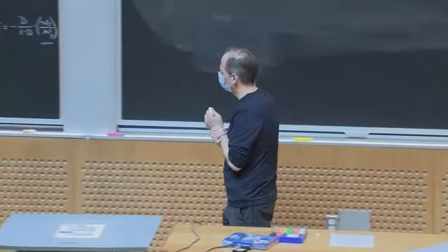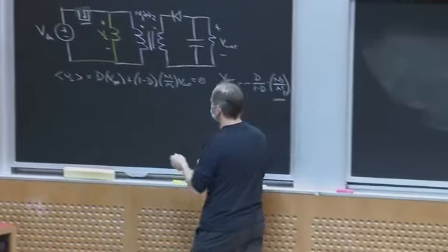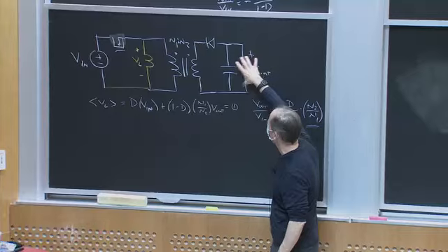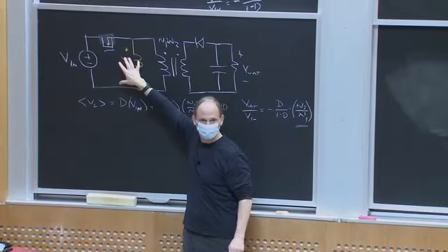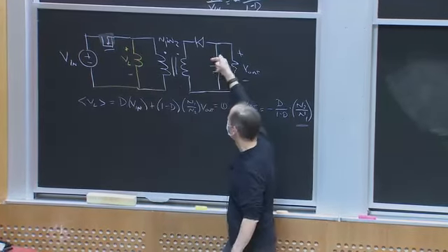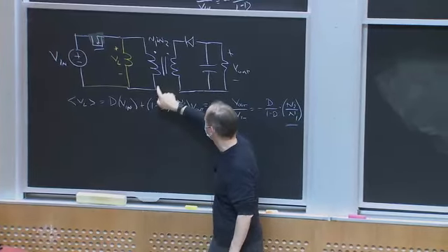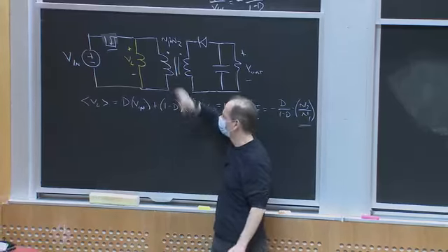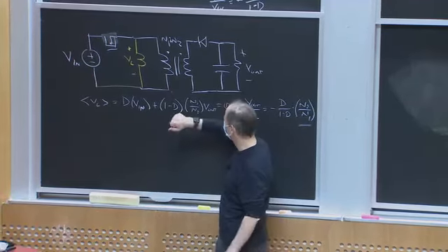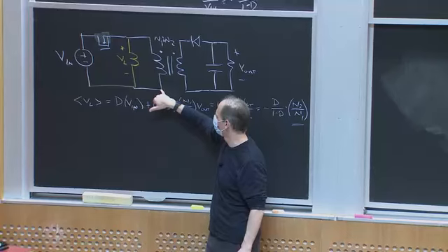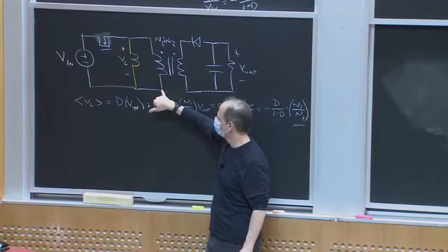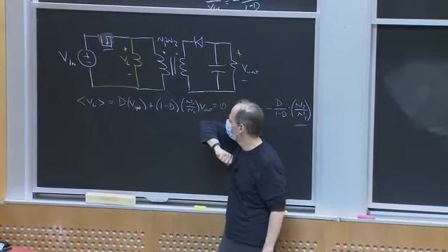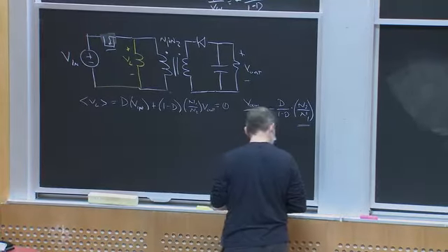What else can we do here? Well, very conveniently, in addition to giving me scaling, notice that this voltage is not referenced at all to this voltage, right? So ideally speaking, there's no way for current to flow from here to here or from here directly to here. So I have the potential to get galvanic isolation, but it also means that this node and this node are no longer referenced to one another, and I can put my grounds wherever I choose in this circuit now.